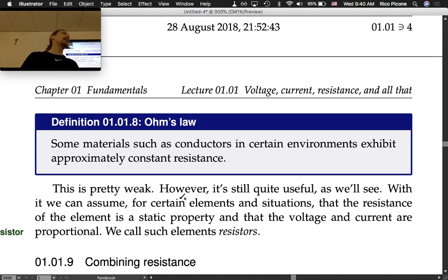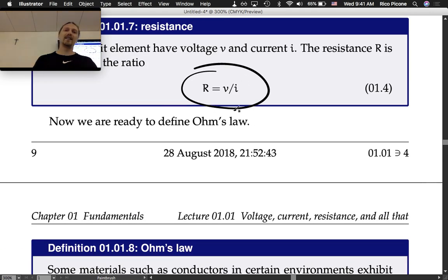What they're saying is these things behave like Ohm's law, okay? Or at least approximately in some operating conditions. And in fact, even those things you buy that are called resistors don't act like resistors in this ideal sense all the time. When they get hot, sometimes they'll change resistance a little bit. If you run too much power through them, you can damage it, and then it really doesn't act like a resistor.